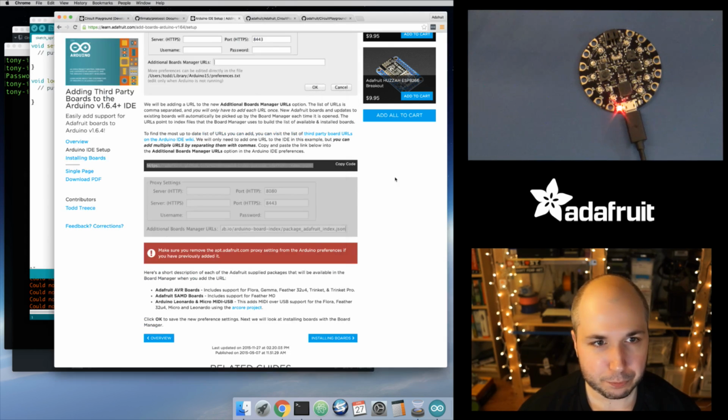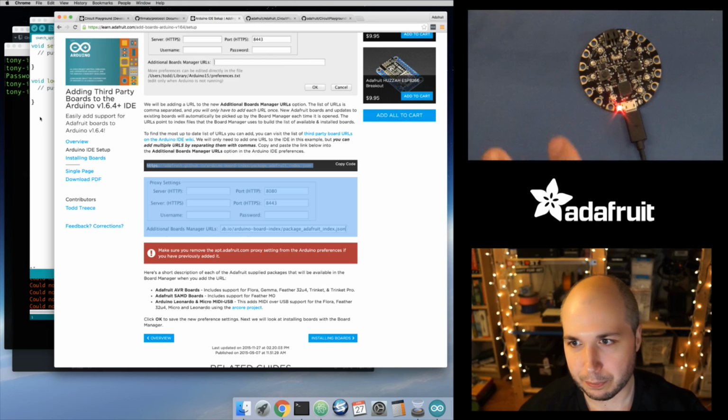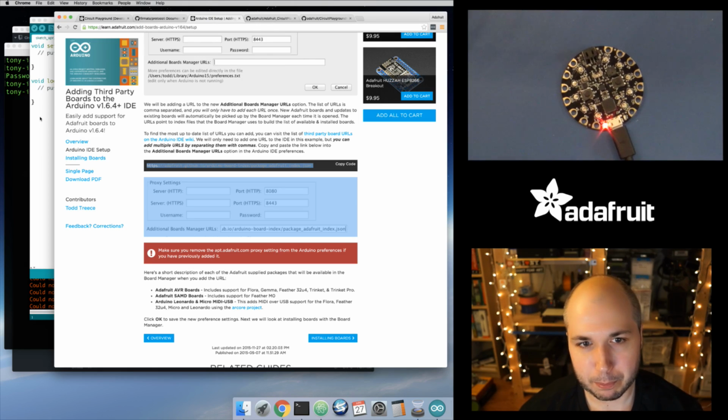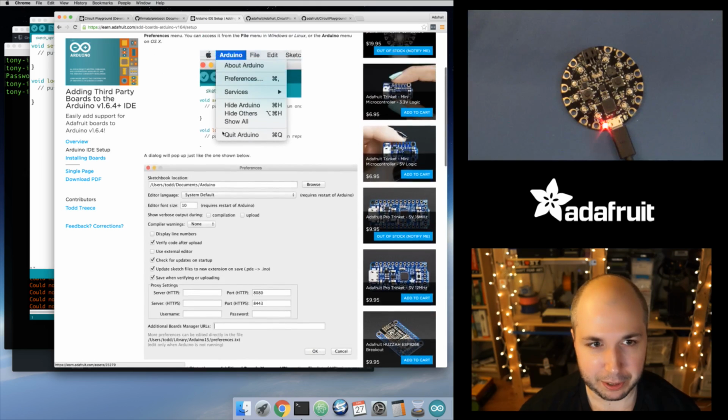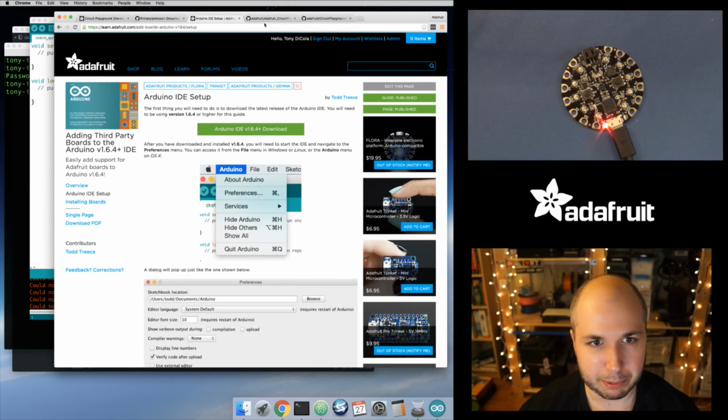Now to use the Firmata Python code, first you're going to need to load up the Firmata firmware sketch on the Circuit Playground board. These developer edition Circuit Playground boards don't ship with Firmata code running on them. Maybe later boards we might actually ship with Firmata code running on them. But for now you need to load up the Firmata library.